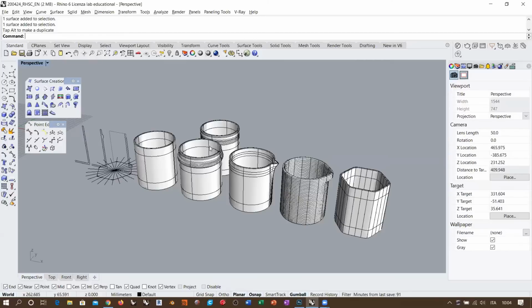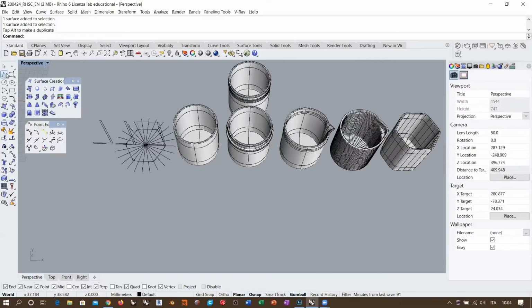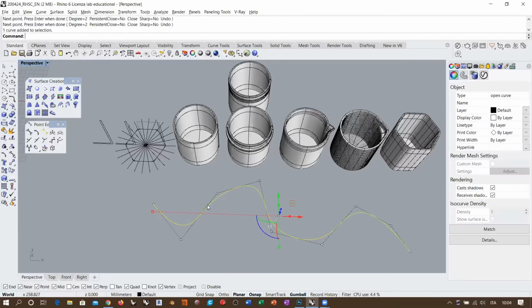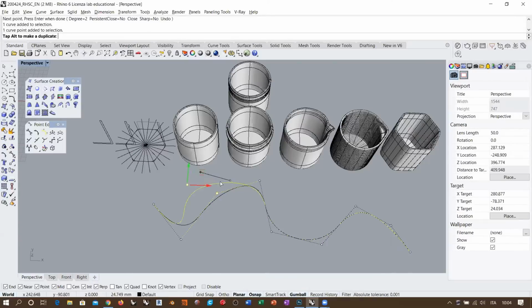But if you work, for example, with a degree 2 NURBS curve like this one, and you start placing your control points like here, you still see that the control points don't lie on the curve. So if you take this point here and move it around, you get no kinks along the path, right? So the problem with the circle is that the circle is not a standard degree 2 NURBS curve. It's a very particular degree 2 NURBS curve.